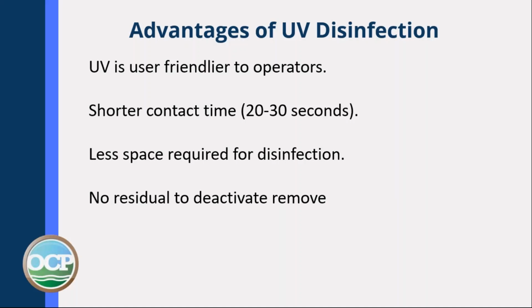Just remember, if you're looking at the bulbs and they're not underwater, make sure you've got eye protection on so you don't burn your eyes. They take shorter contact time, 20 to 30 seconds. Less space is needed for disinfection, and there's no residual to deactivate or remove.